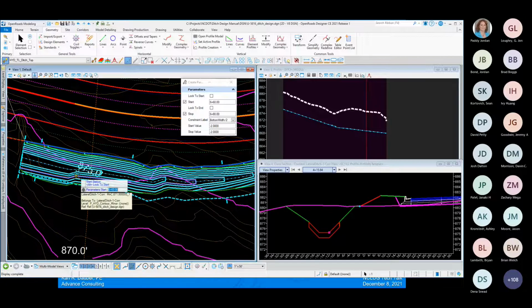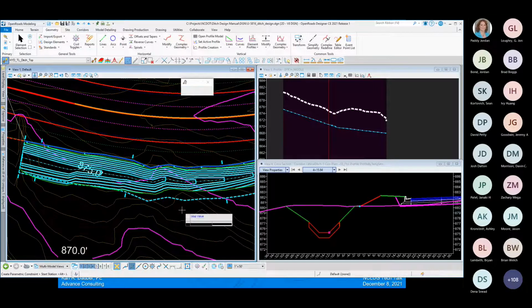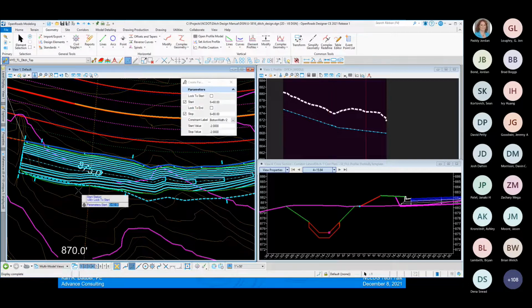I'm going to need a 20-foot long transition, 4-foot expansion times 5. So I'll start the transition at -2 and end it at -4. And then data point to confirm the inputs. So there's the transition.